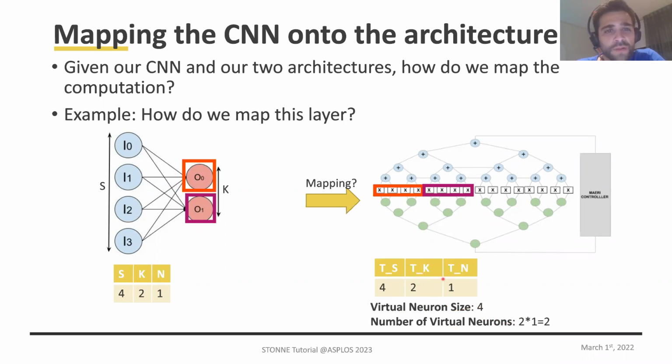And if we had more input batches, which means a larger N and a larger Tn, we could be computing 2 images at the same time, or 2. It doesn't have to be an image. It can be any input, right? But several batches at the same time could be running, right? So that's how convolutional and fully connected layers can be mapped onto our 64 multiplier accelerator, right?